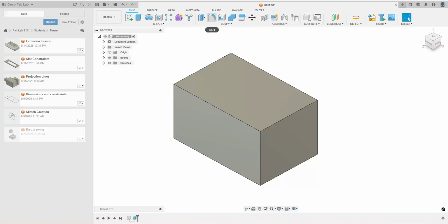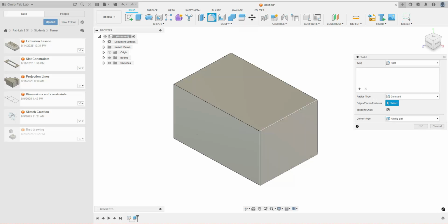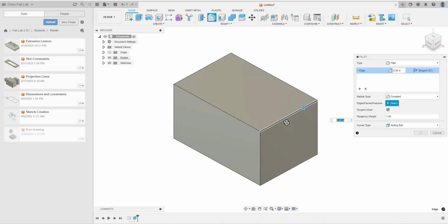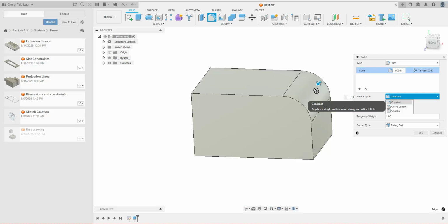And then notice here when you're in 3D mode, right, when you're working with the body, there's a different set of tools, but you still have fillet and chamfer here at the top. So if I want to fillet an edge, just click on it and see that I can round it over. There's a couple different options here for looks wise. Depending on how you curve it, you can adjust some of these settings.